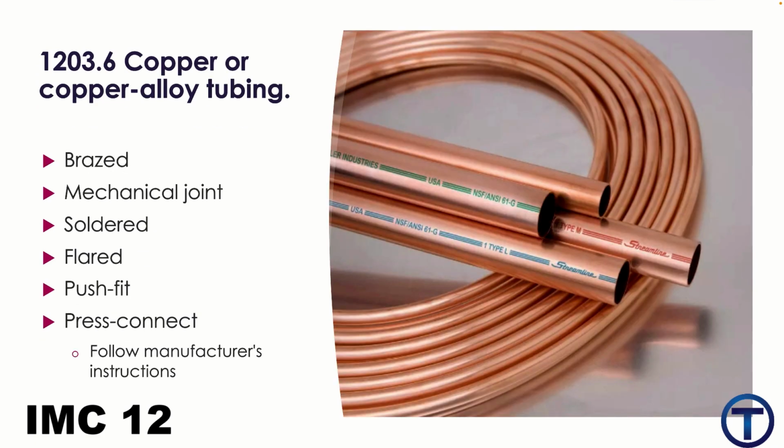Which brings us to 1203.6, which is copper or copper alloy tubing, far more common than the last thing we looked at. It can be brazed. You can use mechanical joints, you can use soldered joints, you can use flare joints, you can use push fit and press connect, if you're following the manufacturer's installation instructions, of course. Copper is a very common pipe used in hydronic systems.